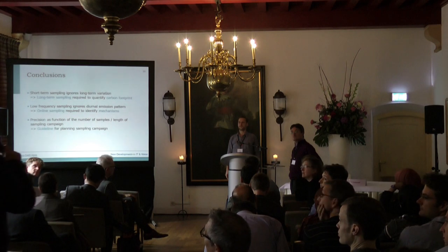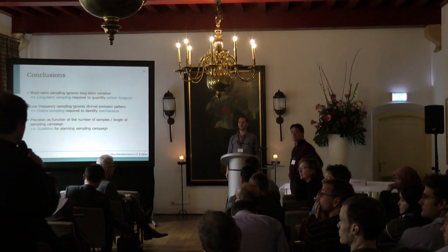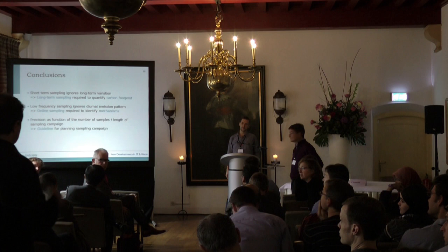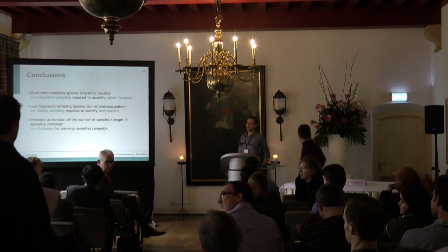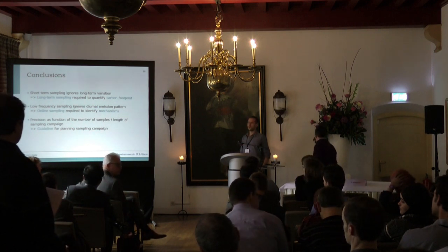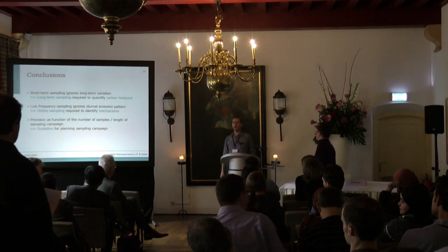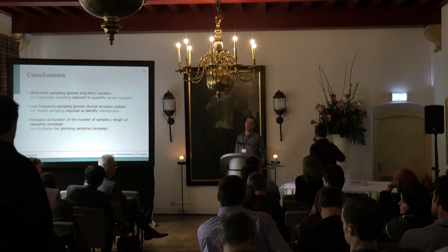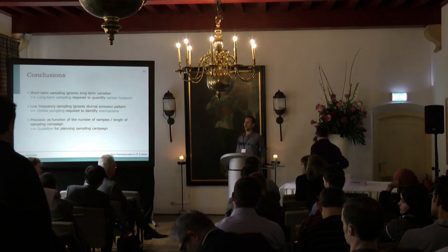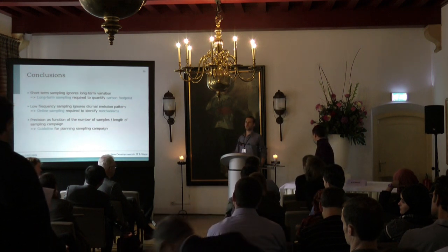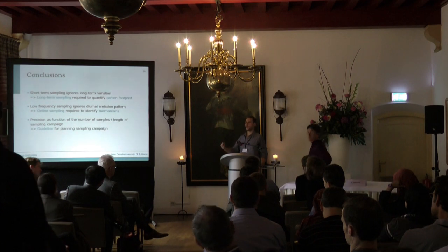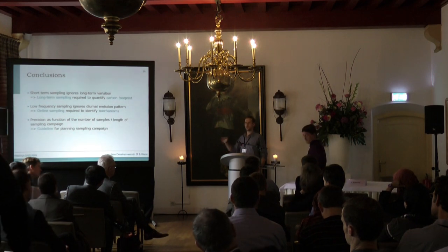Stefan Winkler from Vienna University of Technology. How did you validate your online data? We validated them a few times by taking grab samples that were checked in the lab with the GC. Also our equipment was calibrated monthly, but it was checked more often. Real calibration only happened about once a month because the drift was pretty low.